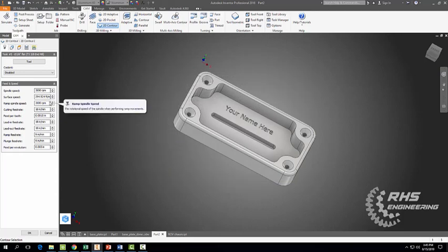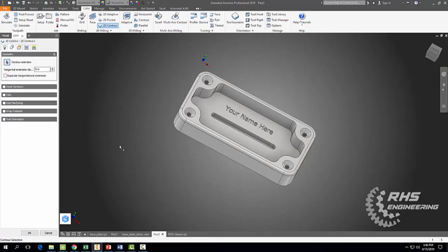Okay, now when you're doing a 2D contour, you want to slow it down. So we're going to use a feed rate of 20 and an RPM of 30. Typically, finishing feed rates and RPMs are a little slower to give you a better overall finish and appearance. All right, make sure your coolant is disabled. And now let's come on over here to our geometry tab.